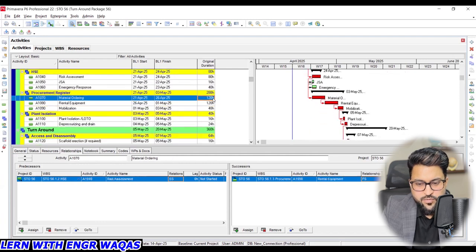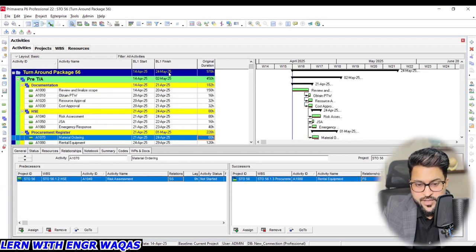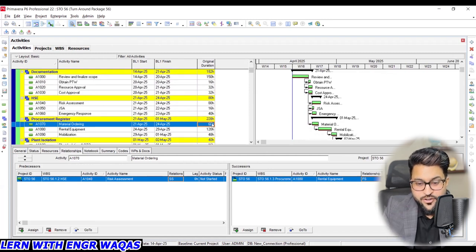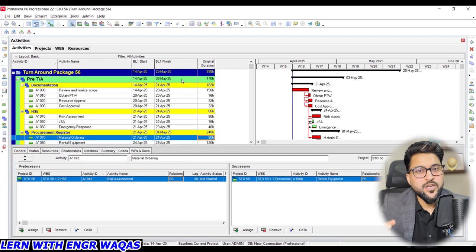I need make over here 60 hours. Then see, it is going to make 24th of May. One day behind that constraint, everything is done non-critical. So I will make it 80, and you can see now this is 25. So this is somehow we are going to check different kind of things to meet that completion date, that is reverse path, when you are going to assign that finish date. So that is the difference between critical path method and longest path.